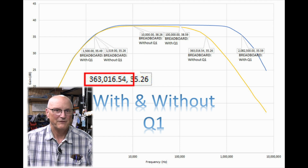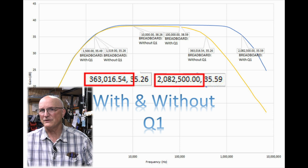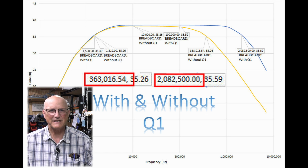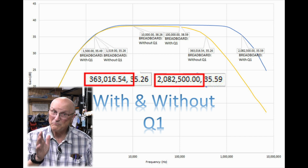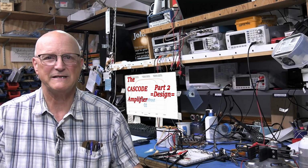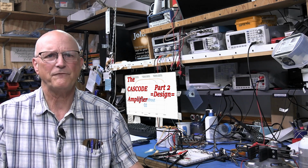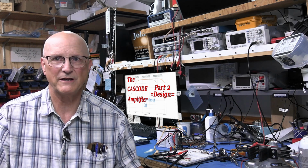But the high-end frequency response of the CASCODE amplifier rolls off at 2.083 megahertz. This is almost 6 times greater than the plain common emitter amplifier. That is still not too bad considering, well, the mess that the breadboard experiment is. I'm sure that if I had created a dedicated PC board using all surface mount components, that the frequency response of the completed assembly would rival that of the simulation.